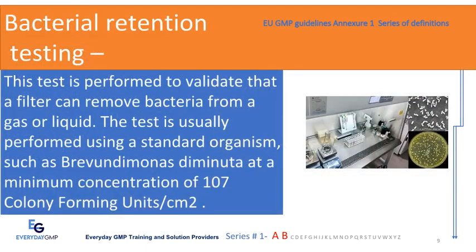Bacterial retention testing: this test is performed to validate that a filter can remove bacteria from a gas or liquid. The test is usually performed using a standard organism, such as Brevundimonas diminuta, at a minimum concentration of 10^7 colony-forming units per square centimeter.